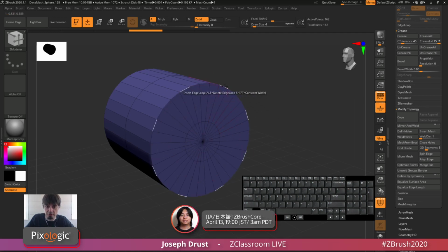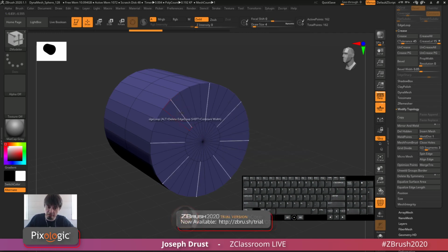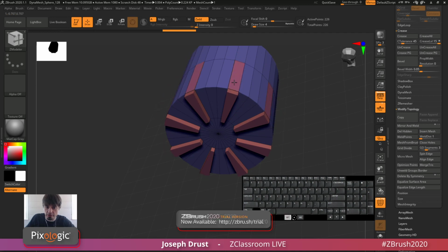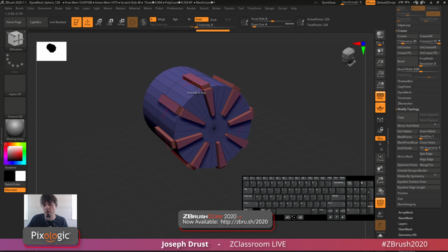As I rotate around, you can see that it performed the actions in 8 ways. If I go to the transform again, you can see my radial count is set to 8. I had 32 sides on this mesh, so I can extrude now at 8 and modify just at those 8 levels, okay? For this one, I want to up it to 16, so I'm modifying one every other and leaving a space in between. Since this was 32, I should have a nice spacing between everything.